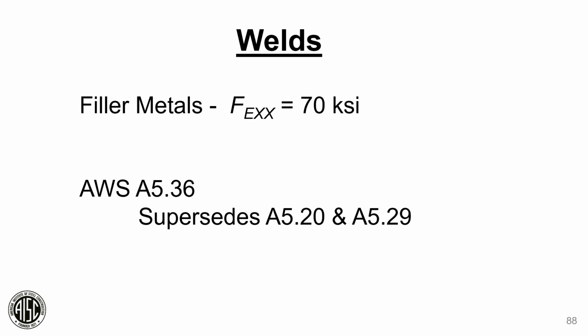When that was developed, it was hoped to supersede A5.20 and A5.29. At this point, they are all commonly available, and it is not expected that A5.36 will supersede them at this point, but you can still specify A5.36, A5.20, or A5.29.